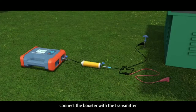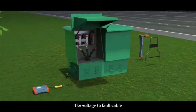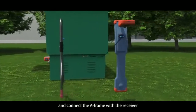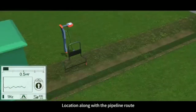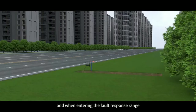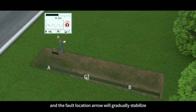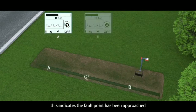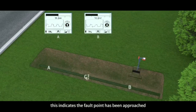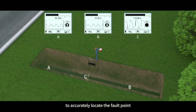Connect the booster with the transmitter to inject a special signal with max 1 kV voltage to the fault cable. And connect the A-frame with the receiver, locating along the pipeline route. When entering the fault response range, the voltage will rise, and meanwhile the waveform and the fault location angle will gradually stabilize. This indicates the fault point has been approached. The device displays the change of the fault direction arrow to accurately locate the fault point.